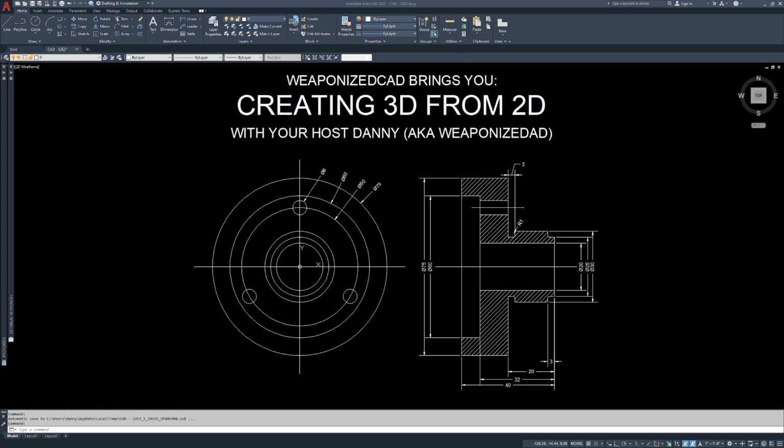When you're building a part, after a while you're going to recognize which commands you need to use based on what the 2D geometry looks like. So in this example, this is a round part. There's one command that is going to build most of this part in 3D for us, and that's the Revolve command.